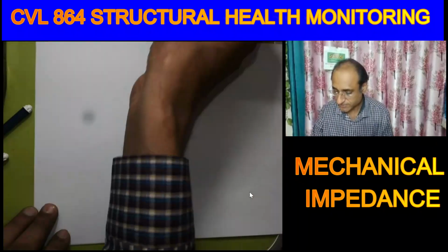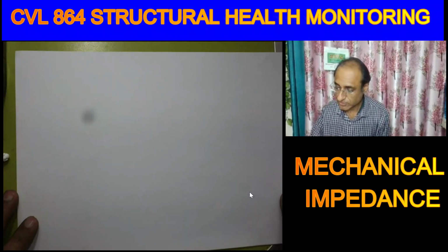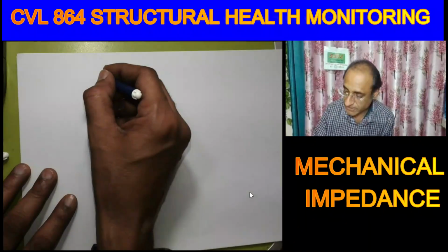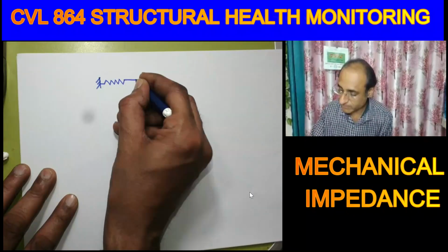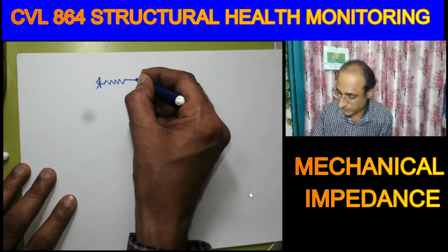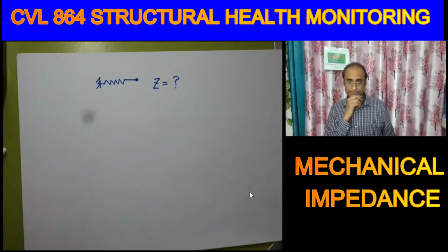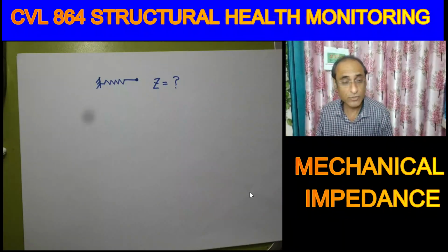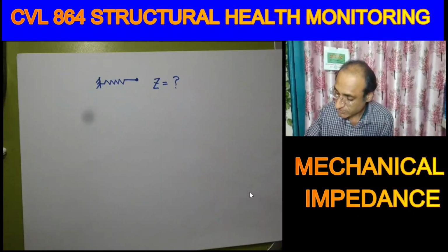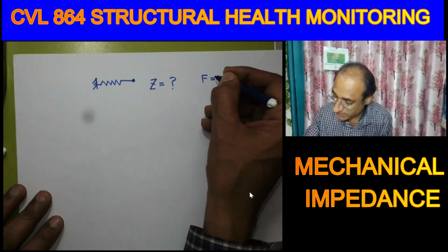Now the last concluding thing is that if I ask you what is the mechanical impedance of a spring, what will be its mechanical impedance? All you have to do is just see the constitutive relation. If you are applying force across a spring, always you will find that force is related to the spring stiffness K by the displacement.